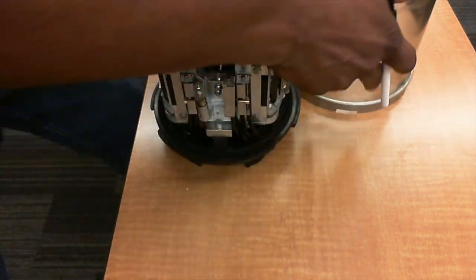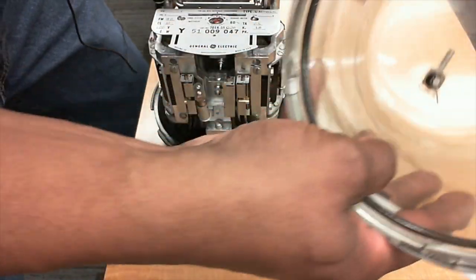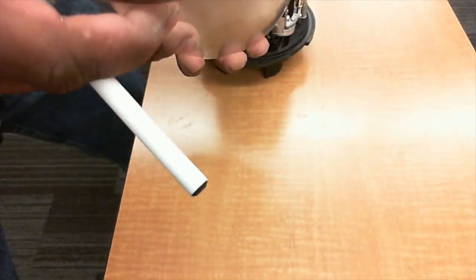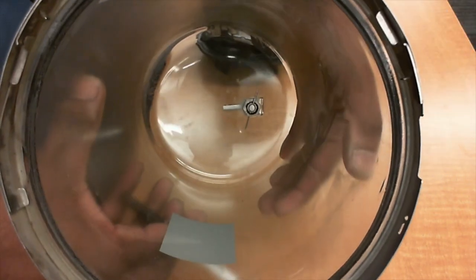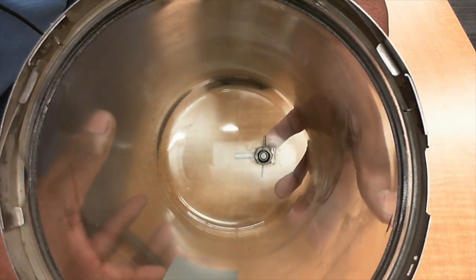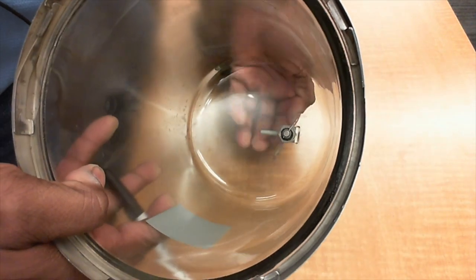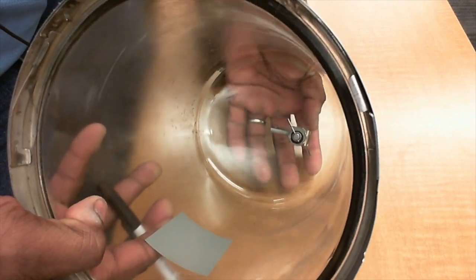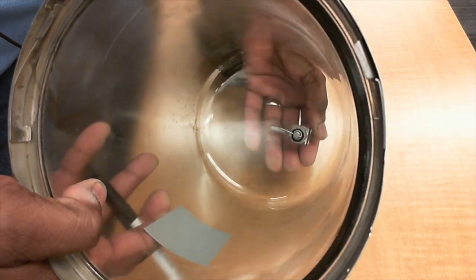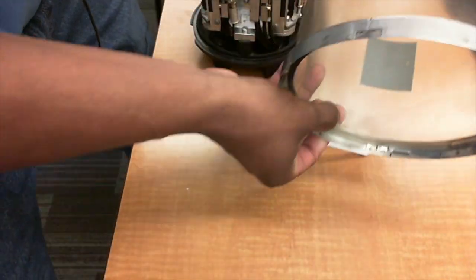So real quick though, the things you want to look for in an electromechanical is this little reset switch in here has a little nut in there. If you see that, and that little arm sometimes is bent. Sometimes you might have to tighten this up just a little bit, just to make sure that the person is actually resetting it a little bit better.